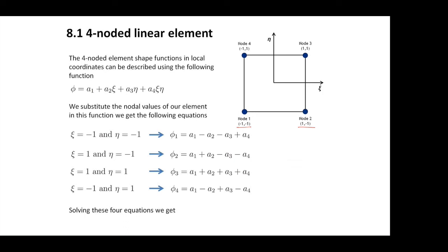All right. Do you have any questions? Because yes, it's exactly the same behavior. Once you have a distributed load, then the linear element will behave poorly. You need to have many of them. If you have a quadratic element, the quadratic element would work with a distributed load much better. So it is pretty much exactly the same. Whatever you have learned about this one-dimensional problem would still be applicable to the two-dimensional problem unless I tell you that this is a different situation. So everything you have learned so far is still completely valid for the two-dimensional problem.